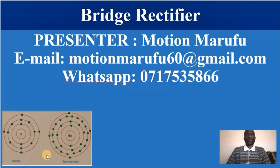Welcome to our 60th video on Electronics 1, and in this presentation we are going to look at the bridge rectifier. In the last video presentation we looked at the half-wave rectifier and the center tap full-wave rectifier. The bridge rectifier is a full-wave rectifier, which means it makes use of both the positive half and the negative half of our AC input signal, and it is the most commonly used of the full-wave rectifiers.